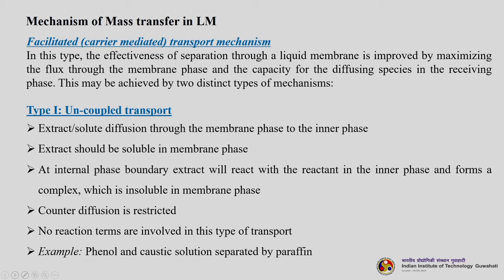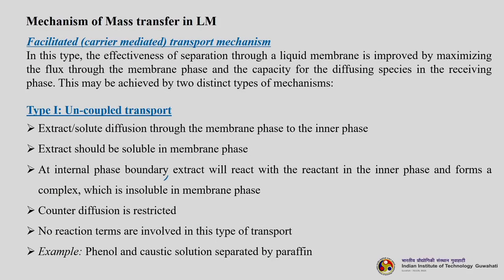The first one, let us understand, is uncoupled transport. Now, here what is happening? The extract and solute diffuse through the membrane phase to the inner phase. Either the extract which we want to remove or the solute will diffuse through the membrane phase to the inner phase. The extract should be soluble in the membrane phase, that is very important. At the internal phase boundary, the extract will react with the reactant in the inner phase and form a complex which is insoluble in the membrane phase.